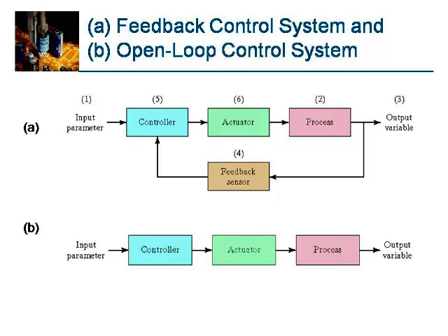Let us see these figures, which indicate the schema of the open loop control system and the closed loop control system. In an open loop control system, there is no feedback signal and a feedback sensor is not required, and the process doesn't have any control over uncontrollable things. If the process does not attain the targeted output set value, there is no correction element here. Whereas in the closed loop system, there is a feedback sensor and the feedback signal is always given to the controller unit where correction is done.